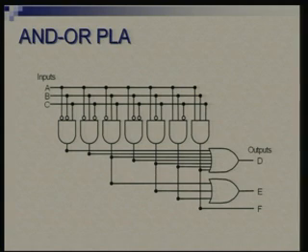So in this case, D is summing output of all the product terms, E is summing 3 of them, F is summing 1 of them, and this pattern of what gets connected to AND gates, which inputs get connected to which AND gates in what pattern, could be worked out in a very convenient form from the truth table, and similarly which product term go to which OR gate is also very easily derivable.